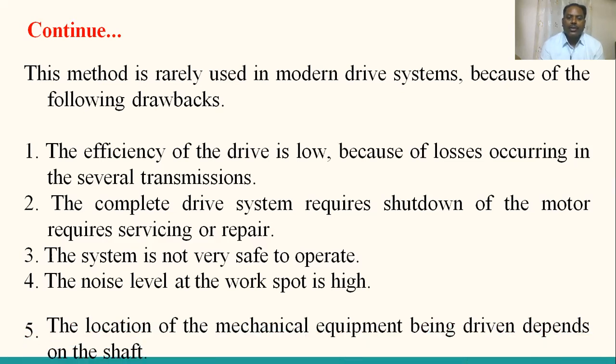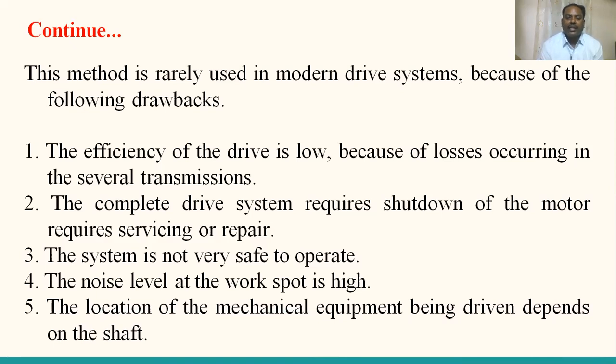Also, the location of the mechanical equipment being driven depends on the shaft, so it is not located conveniently. It may be in some dark places, or at the backside of some machines, which may compromise the operating personnel's safety. Due to these drawbacks, group drives are nowadays very rarely used.